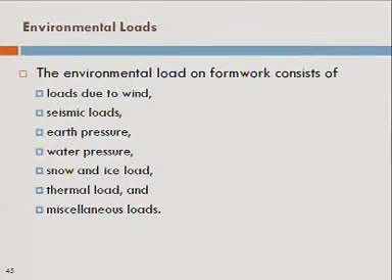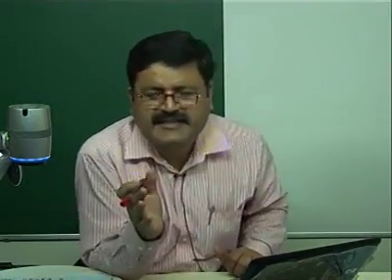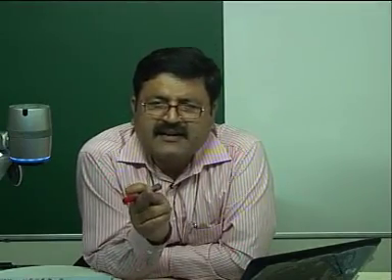When you say motorized, do you mean pumps and vibrators? Not really pump and vibrator. Have you seen Tough Rider? Small dumpers which can carry about 1 cubic meter of concrete. It has maybe 1.5 to 2 meter length, and then there is a driver, and it runs on the reinforcement also. It is light but still with motor. If you just type motorized buggies or motorized carts, these were used in old constructions, especially in USA, and even now they are being practiced.